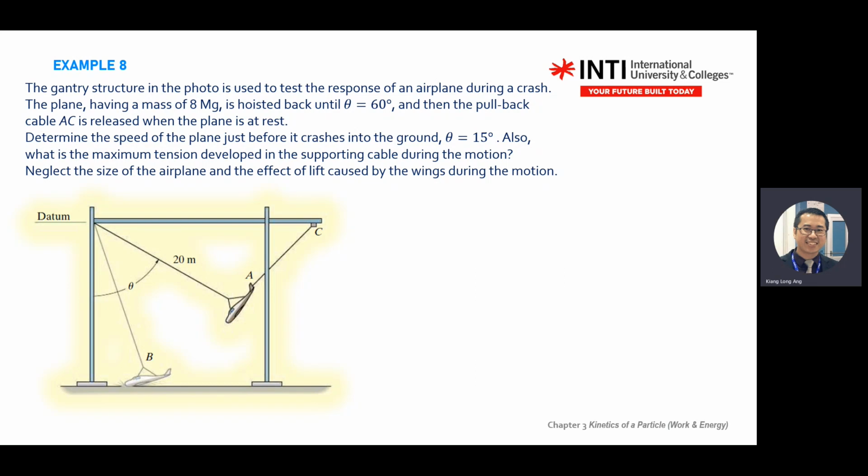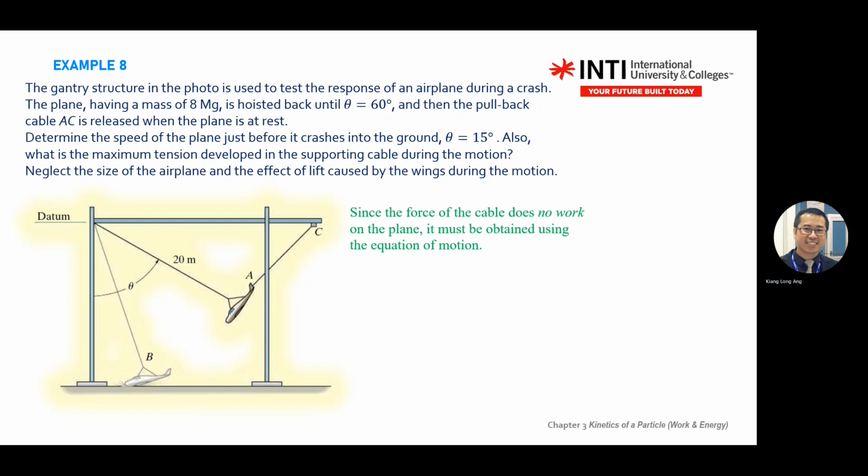Acceleration, you can break into two components, normal and tangent. What is the equation for normal acceleration? v squared over rho. What is a_t? v dot, or the differentiation of the velocity in the tangent direction. There is an equation to calculate rho, 1 plus something, but in this case your rho is given, so you don't need to find it. The rho is 20, fixed.